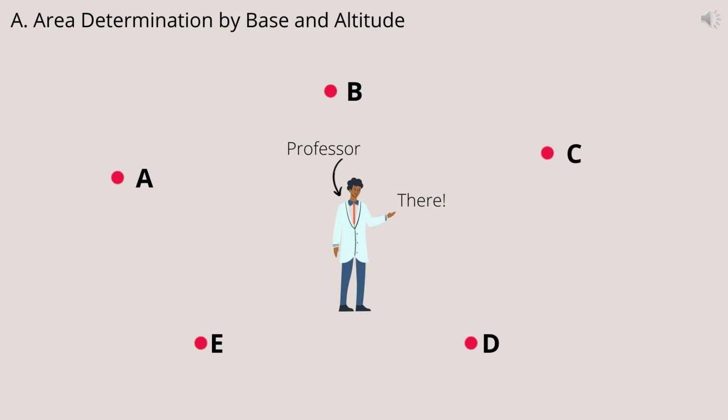So first, the instructor assigns the locations of 5 points in the field, and the students will mark these points with marking pins or chalk. Name these points, which will serve as the corners of the polygon, as A, B, C, D, and E.